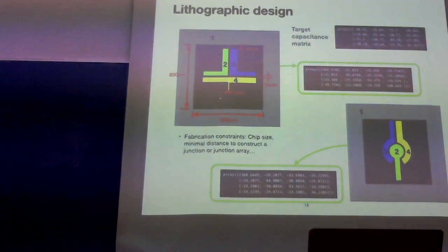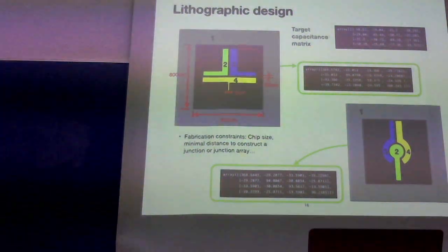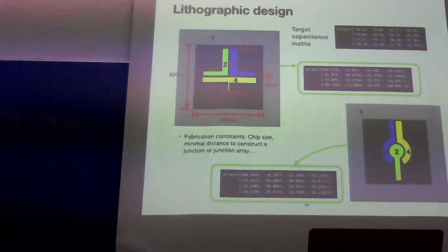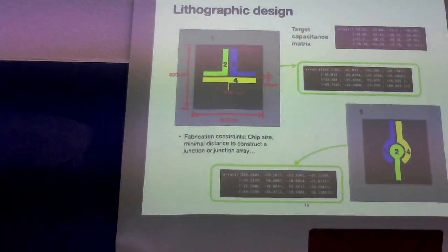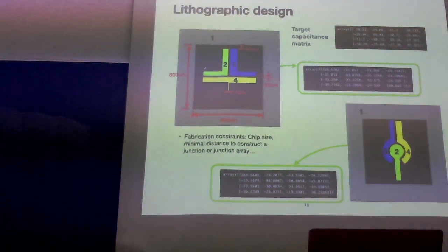Of course, these small features make the electric field do weird things here, and this causes more losses in the dielectric, more dissipation and more problems. So you have to make it round and smooth. Yes, the corners are bad. Corners are bad. I mean, they are rounded, but here you cannot see it.